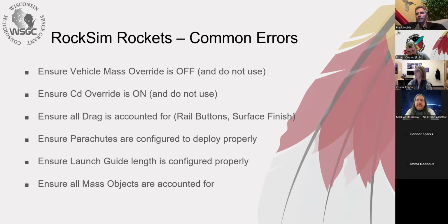Ensure your parachutes are configured to deploy properly. So some people run simulations and they're not thinking about the parachutes deploying, which also affects the drift and the descent rates, all kinds of stuff with your parachutes deploying.